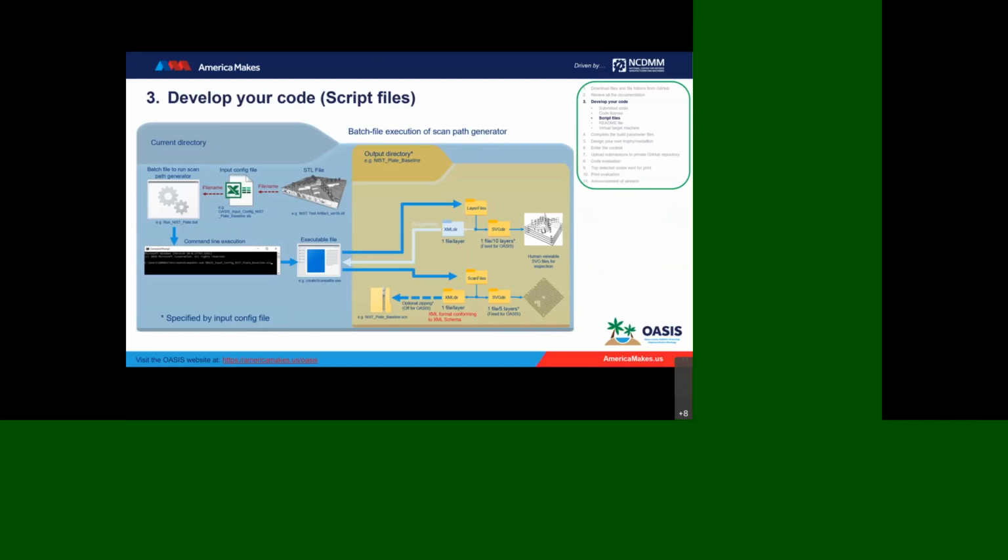In this example, the folder for the NIST plate would be placed in the NIST plate baseline subdirectory. Inside of there, we are expecting two subdirectories, layer files and scan files. Files related to layers from the first slicing of the part would go into the layer file directory. And as mentioned, we are expecting SVG output, so those would be scalable vector graphics.